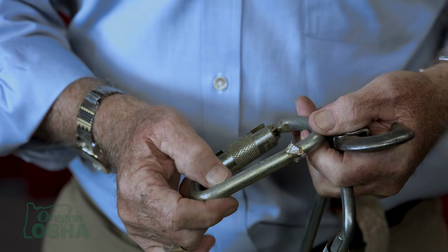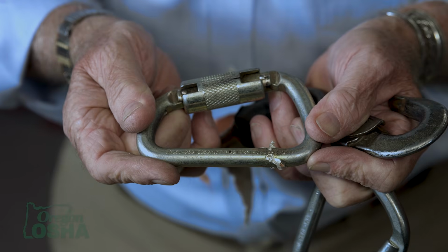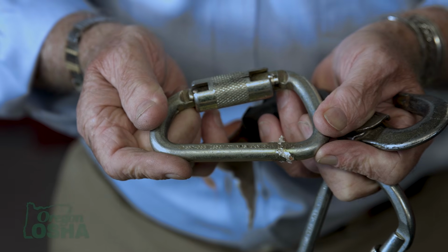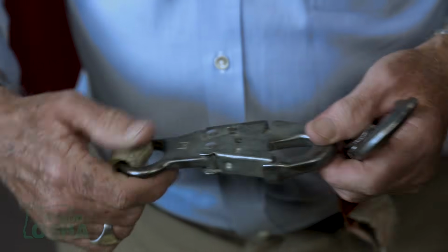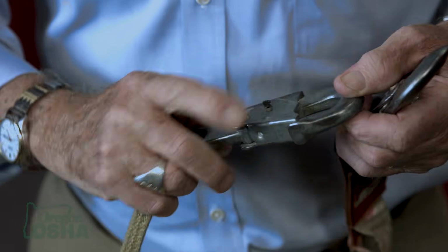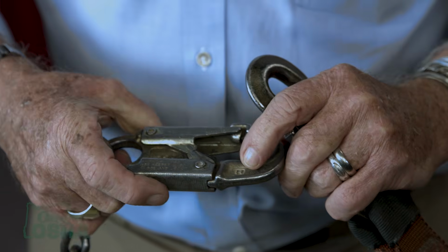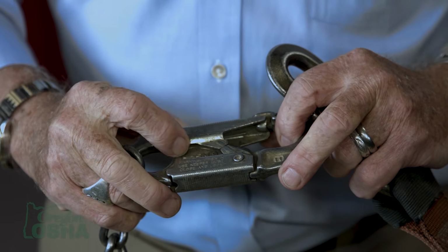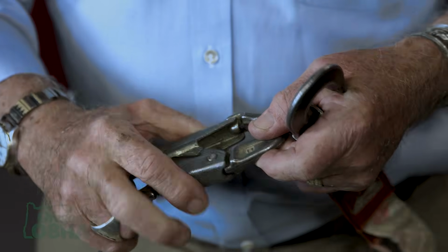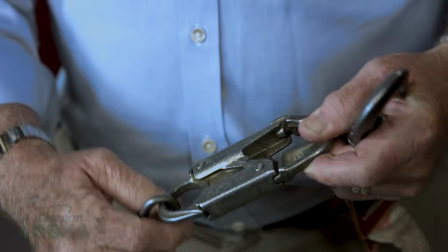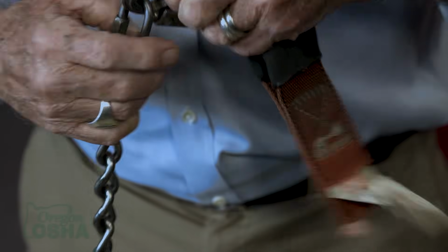Legitimate ones will tell you they're rated to ANSI Z359, and they will give you the strength requirements stamped right on the component. Snap hooks, we want to make sure that they're rated, so we look at a snap hook, we see the information that's presented on it. What we want to make absolutely certain is that they are legitimate. Legitimate manufacturers will brand the hook where it came from. It'll tell you that it's a forged hook and it's worth 5,000 pounds. It will open and close automatically, and it's engineered for what's intended.